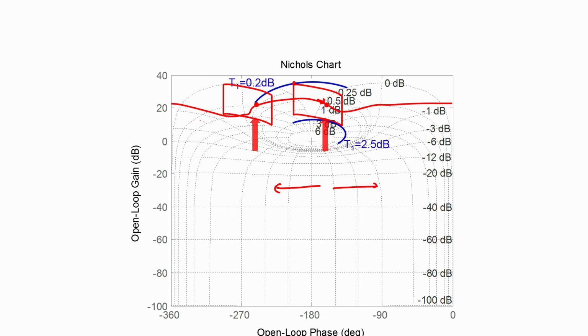So this line therefore represents a boundary above which the loop gain is allowed to lie in order for T1 upper minus T1 lower in the logarithmic scale to be within 2.3 dB, and hence this marks the performance bound on the loop gain at 1 radian per second.